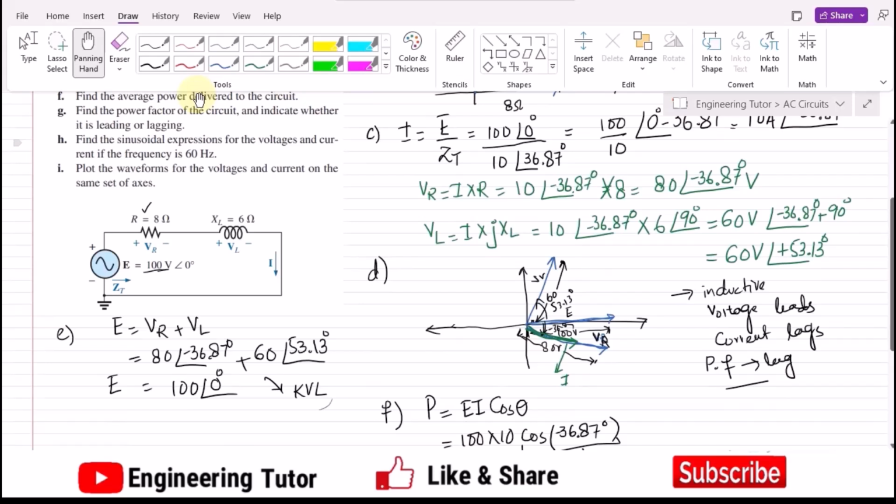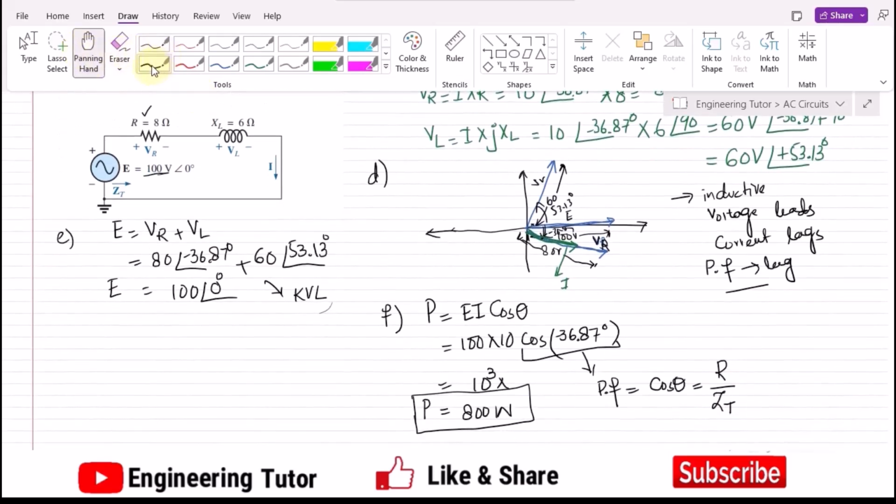So after part F, we have to find the power factor of the circuit, and indicate whether it is leading or lagging. Let me call it G. I have told you that that is cos of theta, the theta which the voltage and the total current have. So cos of minus 36.87 degrees.